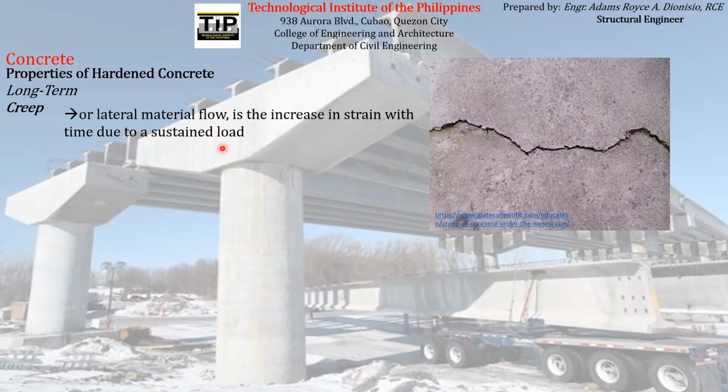Just like what I've been discussing a while ago, the strain that comes immediately after you apply a load is what we call elastic strain. But if the material supports that particular load for a longer period of time, there will be a corresponding increase in strain, which is due to that sustained load. That additional strain being experienced by the material due to that sustained load is what we call creep.